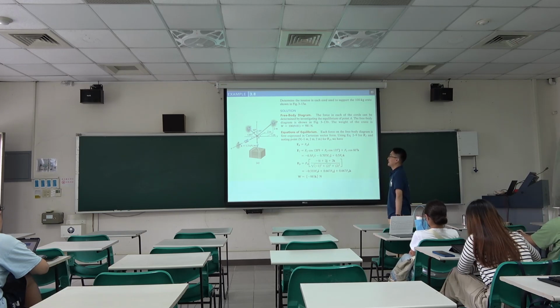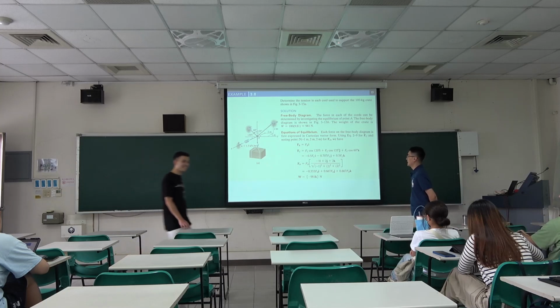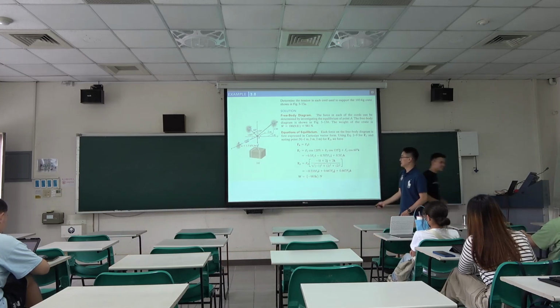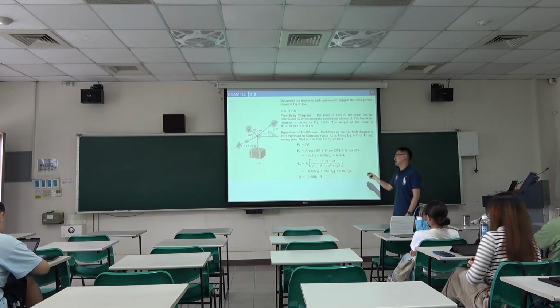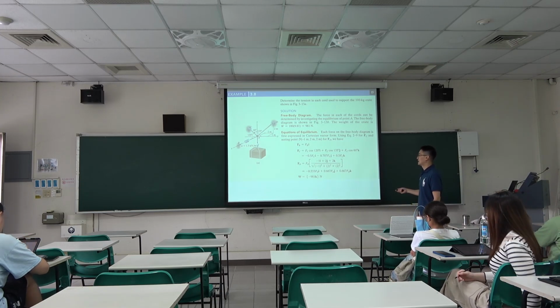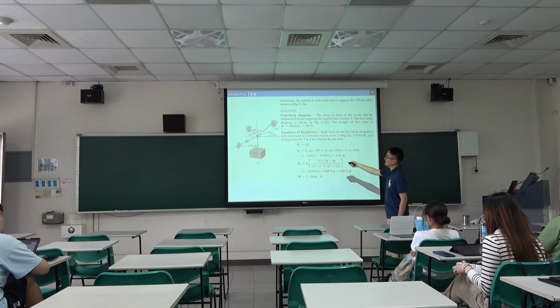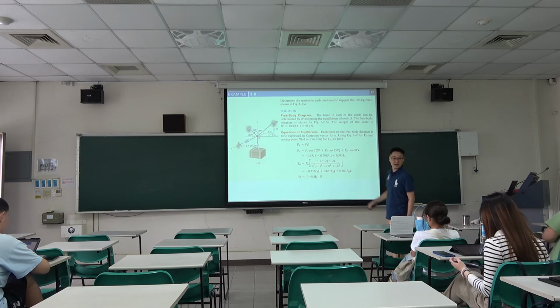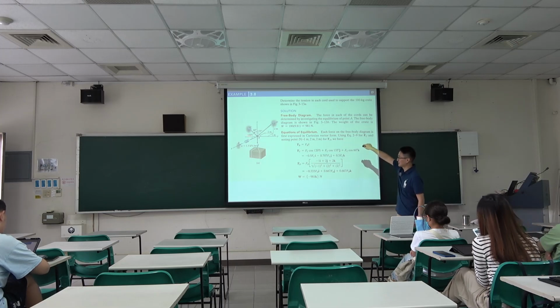When we have the position vector, we can have a unit vector. Then the summation in each direction equals 0 to obtain the equilibrium equations. Then we can rely on the equilibrium equations to work out FB, FC, and FD. FB is along the x-axis, so there is only one component, along the x-axis. Positive is this way.